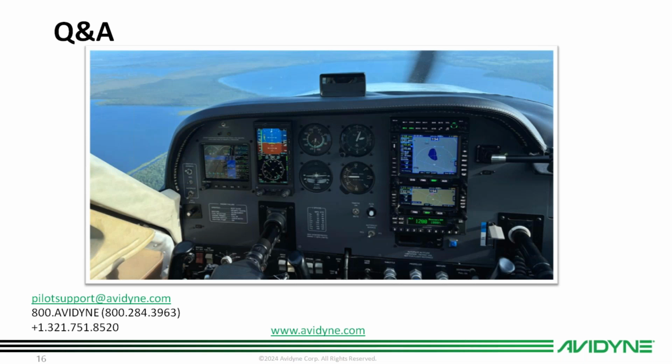If I enter an arrival procedure, can I delete waypoints? For example, if the arrival is waypoint 1, 2, 3, and 4, can I delete waypoints 1 and 2, leaving just waypoints 3 and 4? I don't think you can actually delete parts of the arrival, but you can do a direct to that waypoint.